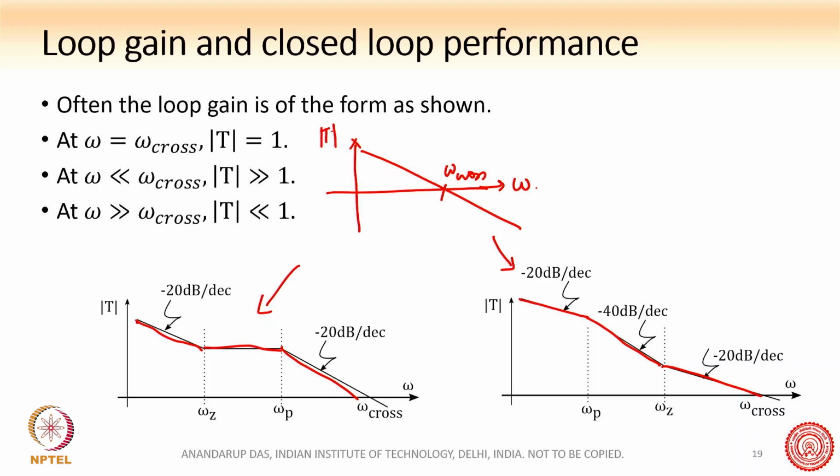So in between, across this whole omega axis, there are modifications, but the overall trend is that the loop gain has a very high value close to DC. This side is DC, omega equal to 0, and this side is high omega, which corresponds to the switching frequency, right?